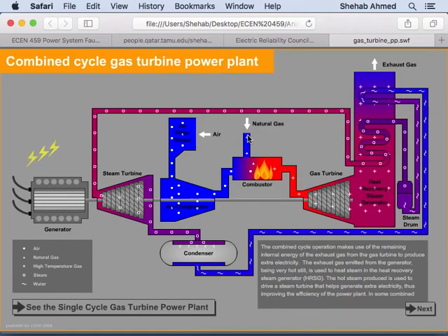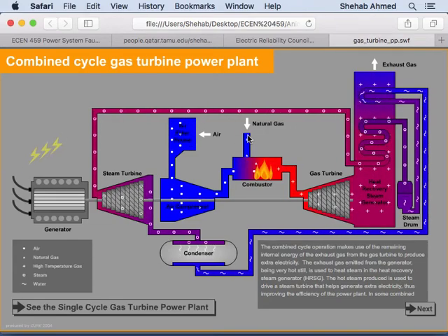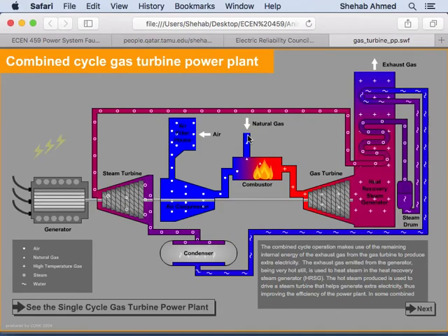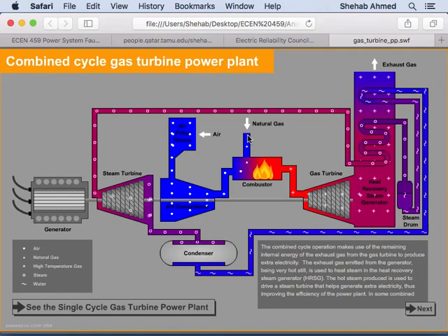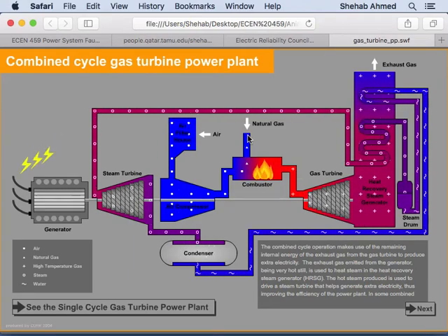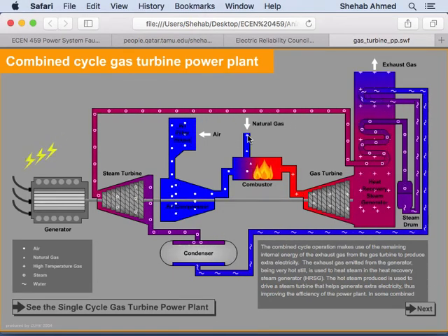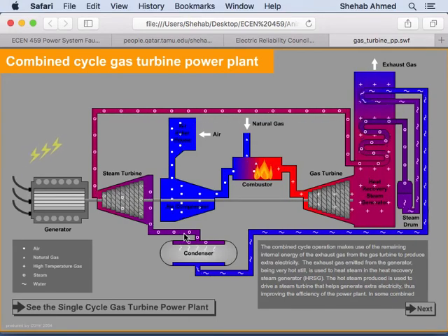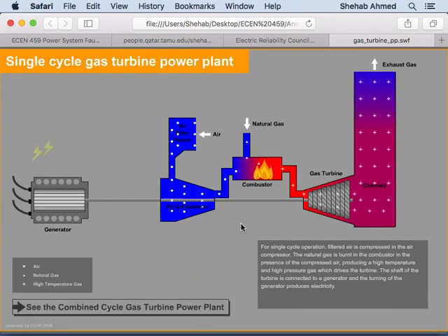these take a longer time. It's a bigger process. There's steam in the process, cooling of steam in the process. It's a slower process. So these are mainly called base load power plants. They provide the base load. We know that this building, for example, operates at a base load of a megawatt, right? But when all the students are in the building and the air conditioning load is high, etc., we know there are peaks. And then the night goes down, peaks, and then the night goes down. So there's a base load. The base load is typically provided by these slower power plants, right? And then the fluctuating loads are typically provided by these faster power plants, right?